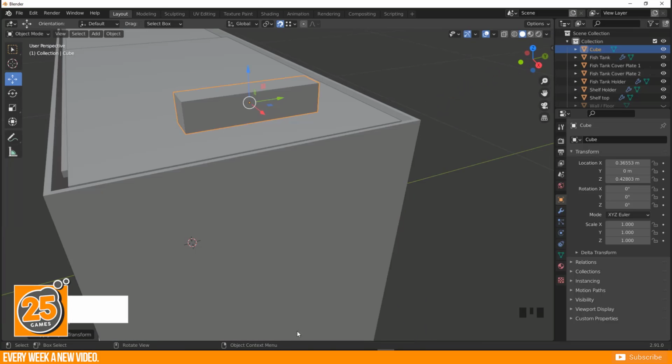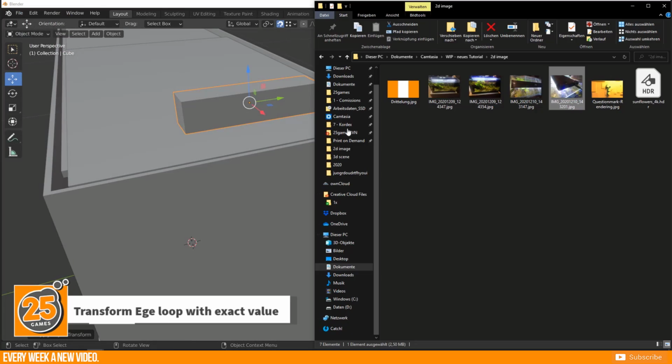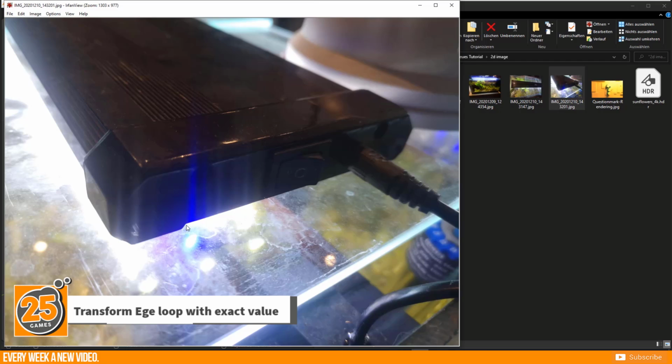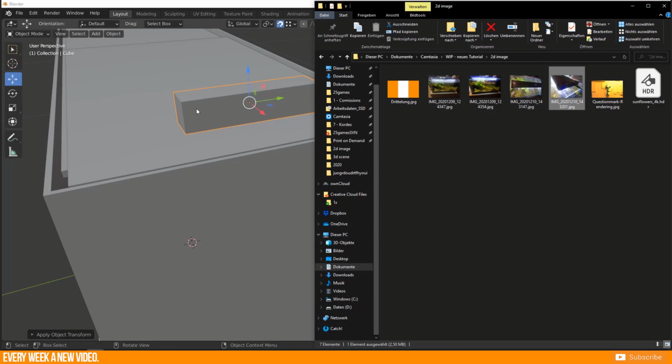And before I do any bevel, I want to add some edge loops. And those edge loops should be good for finding this corner here. So I take the measurement, and it is from this corner to this position 2 centimeters. So not at all 2.5 or something like this. So 2 centimeters from this position, and for sure at the other position as well. And I need to do this before I do the bevel. So how can I do this?